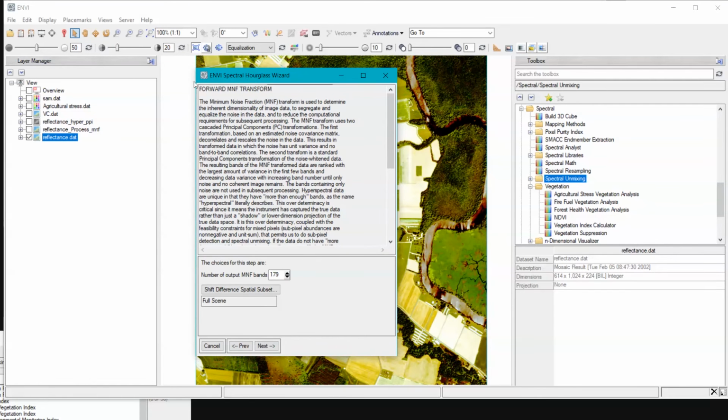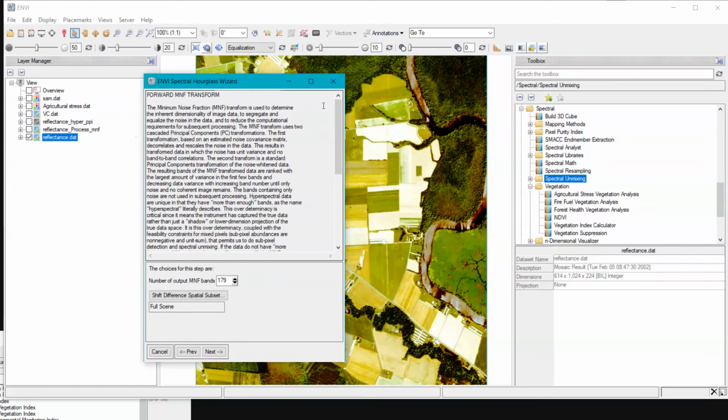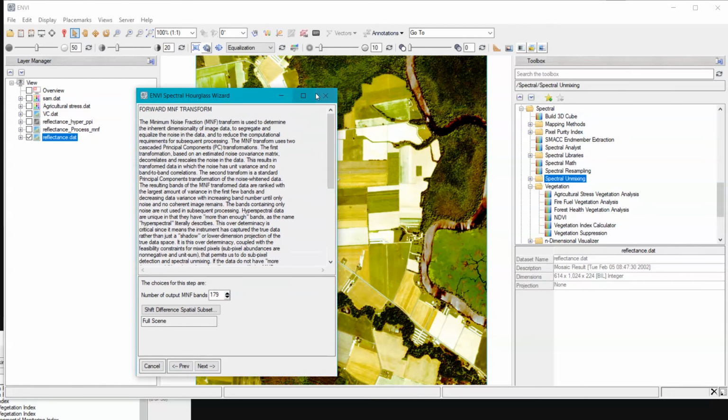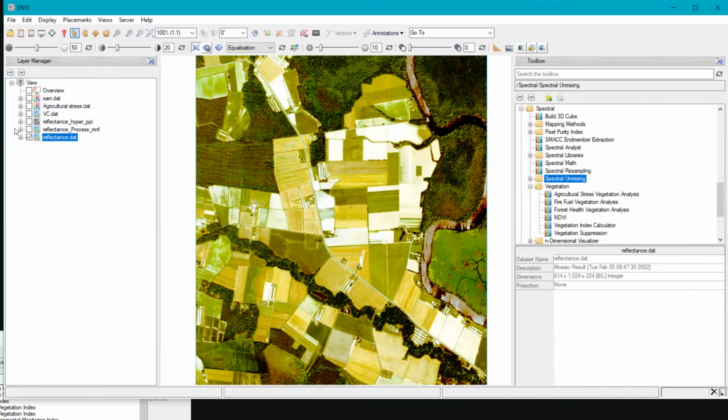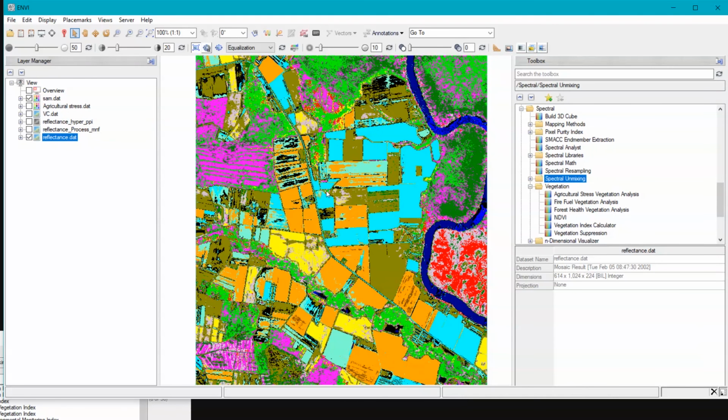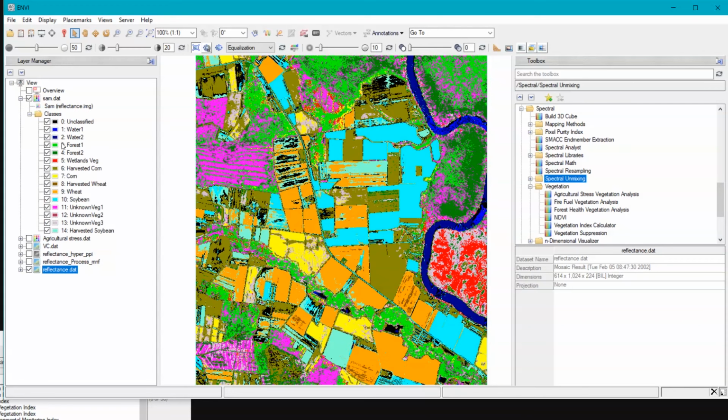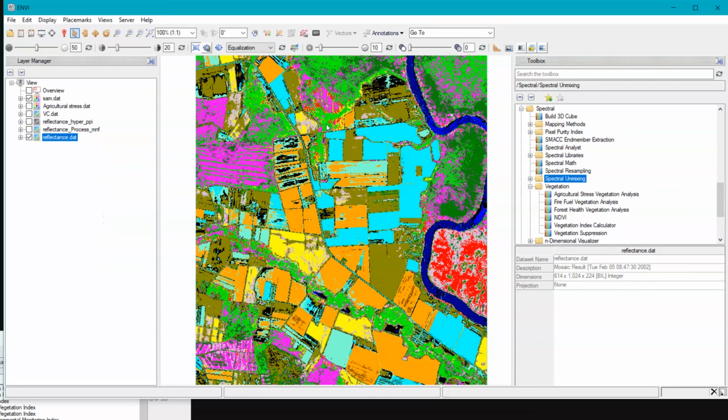So this is hyperspectral imagery of Everest. As can be seen, there are some 224 bands. The exclamation marks along with the band mean that these may be noise, these may be bad bands, or these may not have been identified. Also, working with some 200 bands is not very feasible for the user. So using the process of MNF, that is the noise removal process, and doing a pixel purity index, ENVI can reduce these to some 179 bands that are actually used for the analysis.